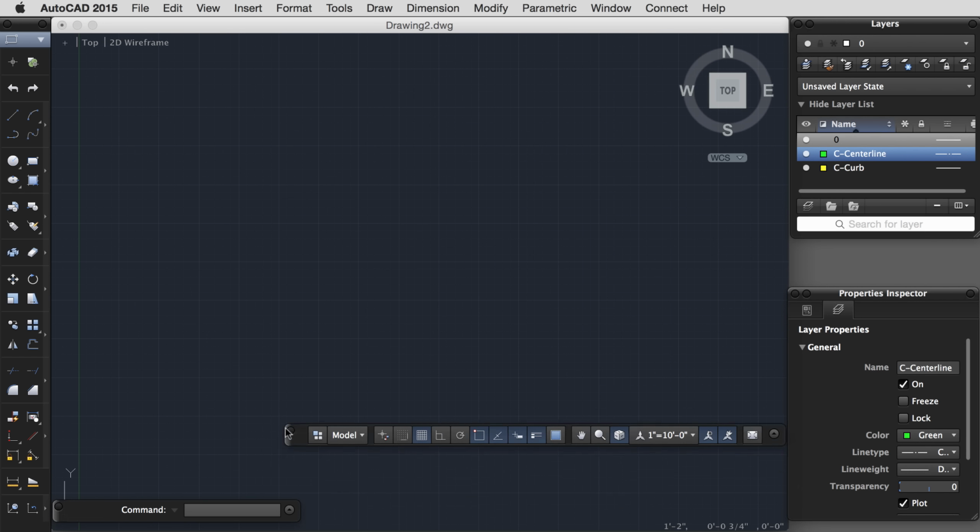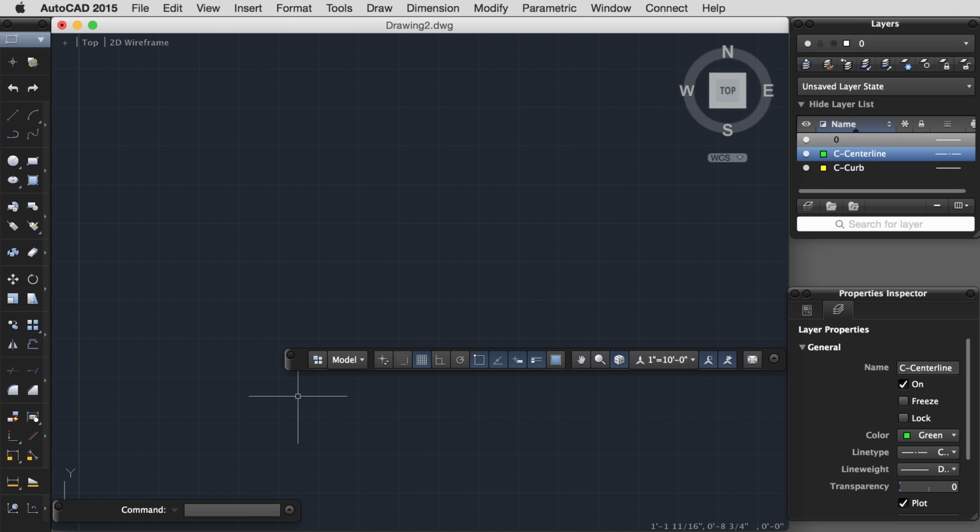Since this preliminary tutorial is primarily about helping you understand the interface and set up your drawing properly, there's just one more thing I'd like to show you. I'm going to pull my Drawing Aids toolbar up a little bit so that you can see. If I click on the Model tab, you'll see I have Model, and then I also have Layouts. And layouts are a way to access what we call paper space, which means that we literally get to see your CAD drawing, how it would look on paper.